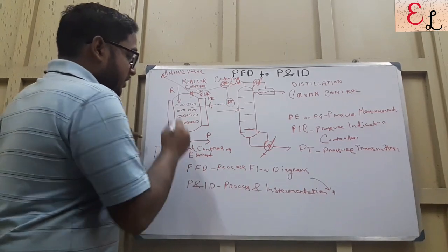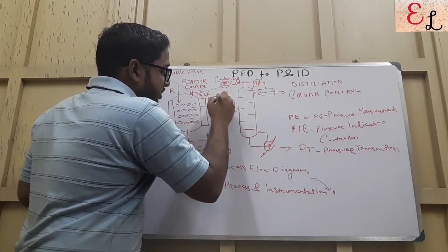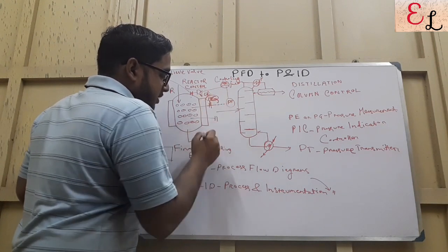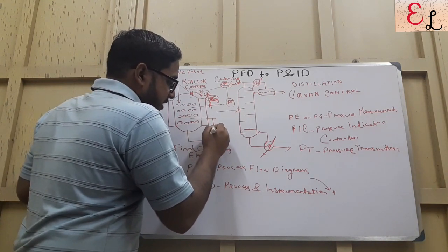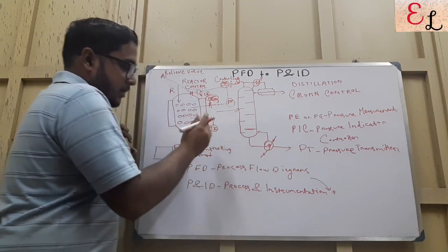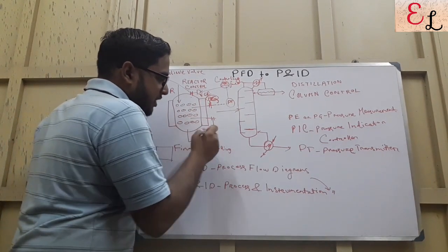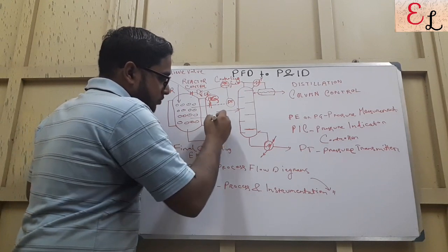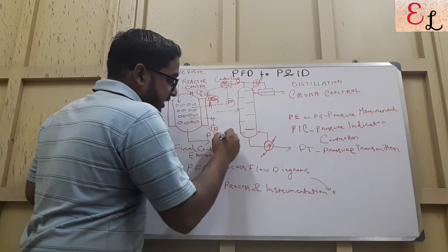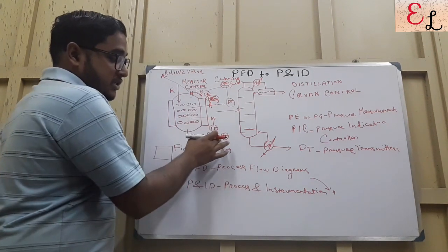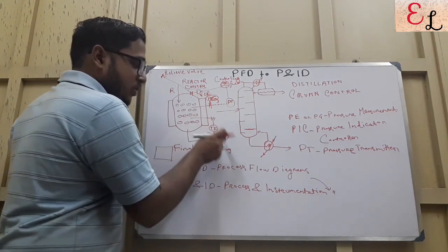Now coming to temperature, if the temperature of the reactor shoots up, so we need to keep this is pressure gauge PG, let me write this PG. So you basically would see that this is my temperature element, TE, it's being shown like this, branching coming out of the main stream trying to measure the temperature. When we measure the temperature element, we would further move on to the TT, that is the temperature transmitter, which is converting this pneumatic signal into electrical signals.